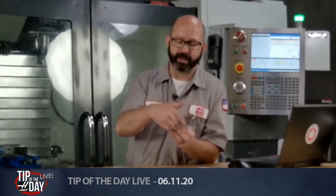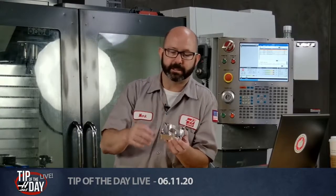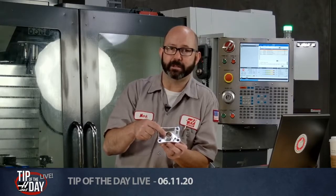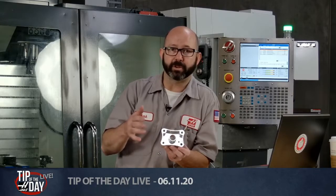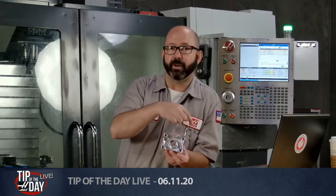If you've got a pocket like this, I did this thing with a CAM system, pocketed out around this. What's unique about this pocket is that it's got a big boss sticking up in the center. G150 is nice. All you have to do is define your perimeter shape. And you can do that, and they'll have a P and Q value, kind of like a G70, G71 cycle on a lathe. So it's a subroutine that defines the shape of the pocket that you want to machine. Once that's done, you answer the variables, and it machines it out.